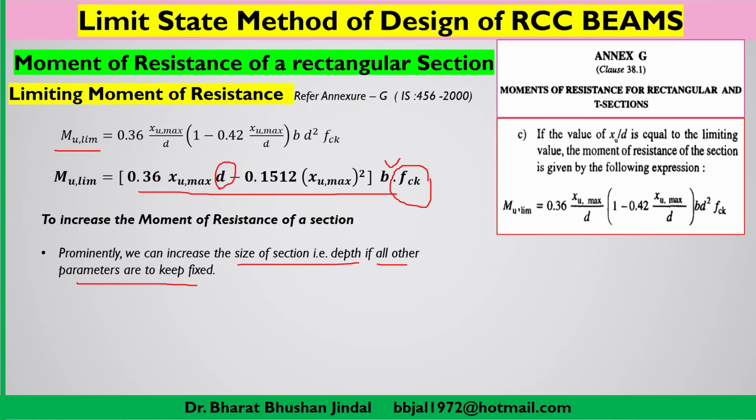If you increase the depth of the section, definitely this first part of the equation will increase and the second part will not be much affected. So if the xu max value is fixed and it is based on the value of d, in simple language we can say, if you want to increase the ultimate or limiting moment of resistance of the section, you can increase the depth of the section.